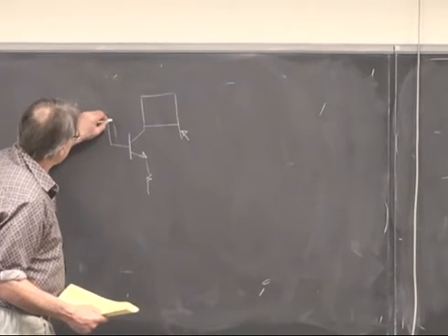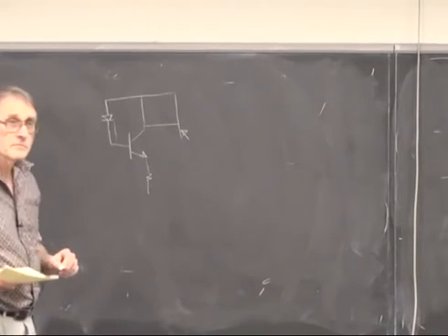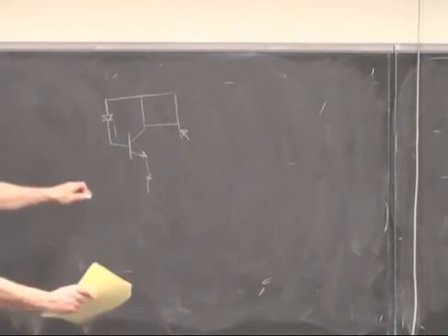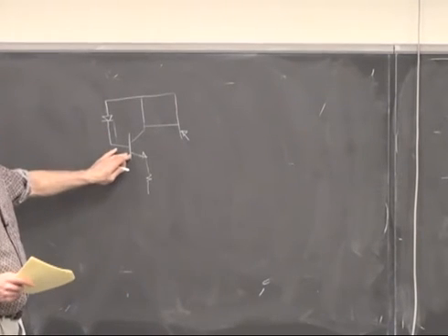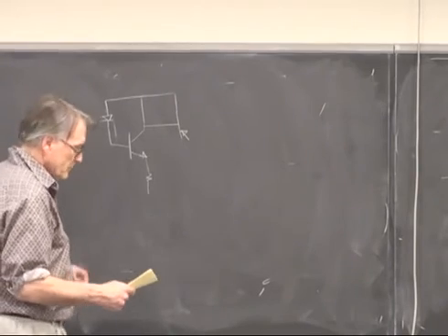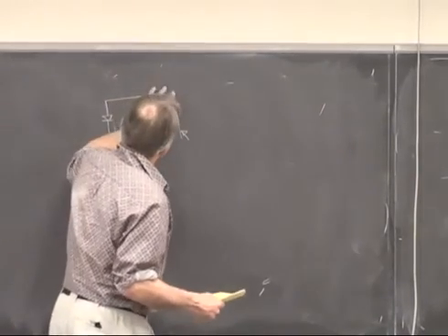We're going to put a little bit of a threshold in here by putting a diode right here. That gives us 0.7 of a volt slack before we start turning on this transistor at all. And that's crude.